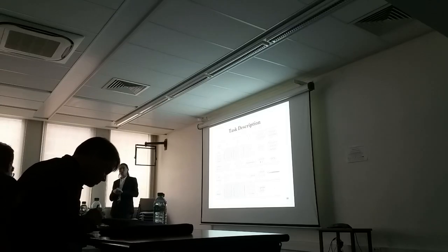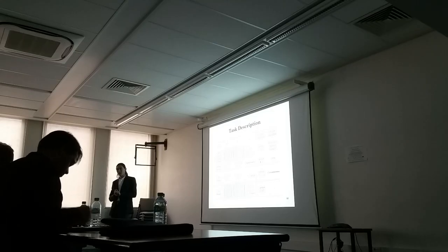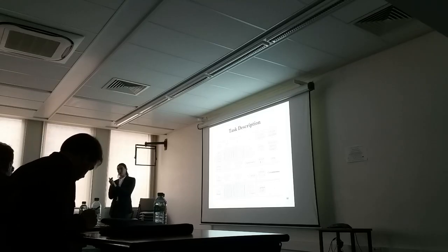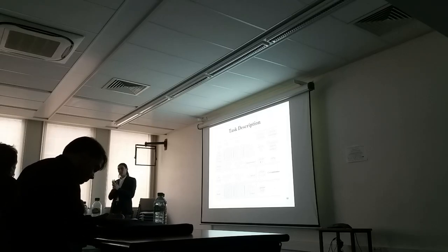It's possible to make very precise calibration of those sensors, but it takes maybe a week for each tactile sensor, because there are temperature changes, and due to the wear, each time we manipulate an object, the surface changes. So it may be difficult to use this kind of sensor in an industrial environment where the temperature changes. You have to regulate the temperature in the room if you want to use this kind of sensor.